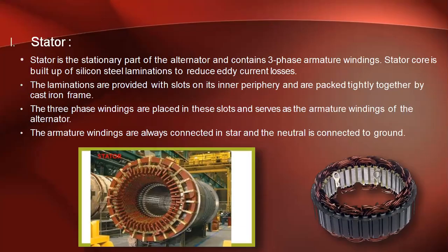Three-phase means that for each phase there will be a 120 degrees phase difference. The armature windings are connected in star, and neutral is connected to ground. You can see the winding of a stator in these diagrams.